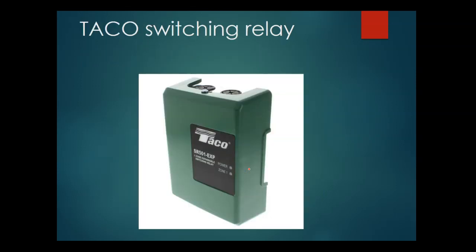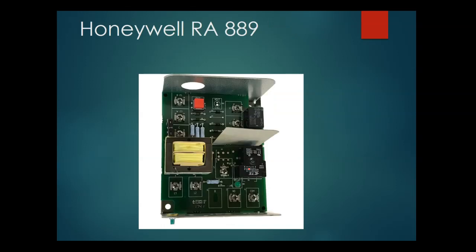This is the new one. It's the Teco relay, and this is the Honeywell relay. Again, the same connections. These are the thermostat, red and white, TT. As you see, they have changed. They have colors now, and we have common here, and L1 and L2, and the X1 and X2 will go to the pump. And usually you will see the connection of the wiring in the back of this cover if you want to connect using the new relay by Honeywell.